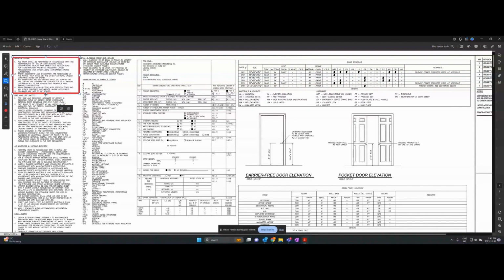Basically, they never ever want you to scale a drawing, but you can, but we just have to verify that things are actually the way they are. So if you take a look at this right here, we have a door. We know this door on a scaled drawing is 1/2 inch equals 1 foot. So we know that from here to here is 3 feet. We know 1/2 an inch. So if you're measuring out with a tape measure, we know that 1.5 inches equals 3 feet. If that's the case, then you can do the math and scale off it. If it doesn't work out, then we have to go by all the dimensions on the drawings. And if a dimension's not there, again, we can send an RFI in, request for information.